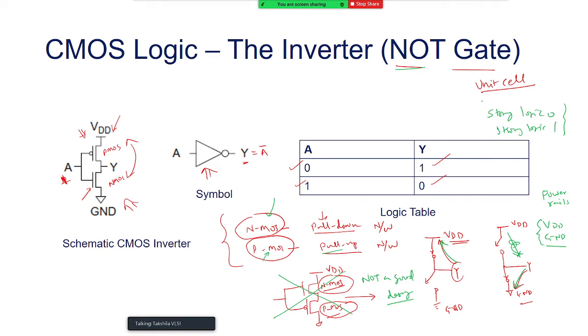And we will also explain as we progress ahead why they will produce the degraded logic. They will work. It will also give you Y equals A bar, but the output Y will not be a strong logic level. It would be a degraded logic. It means I want a logic high at the output because of the switching, but I will have a slightly lower level than the VDD. So if I am operating 1 volt as a VDD, I will have 0.9 volt.